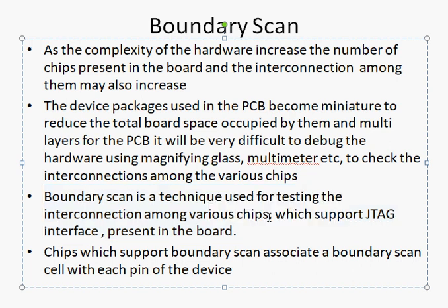Various chips means integrated circuits. You might have 3 or 4 integrated circuits, and you may use this boundary scan method to identify if there is any connection break or make. Every JTAG interface would use this boundary scan method for figuring out the connections.